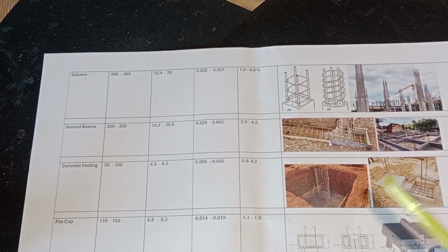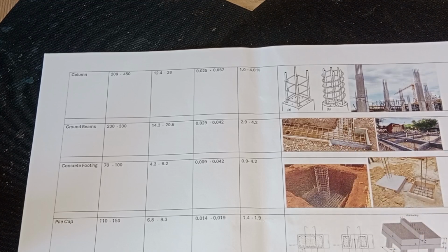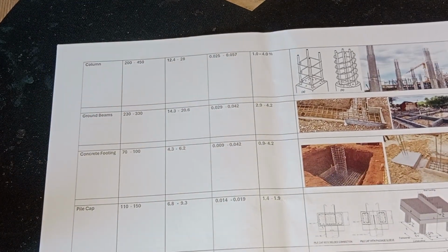You see here, that's what we call ground beams, connecting foundation elements together. It is about 230 to 330 kilogram of reinforcement per cubic meter of concrete, and that's about 2.9 to 4.2% of the section. And concrete